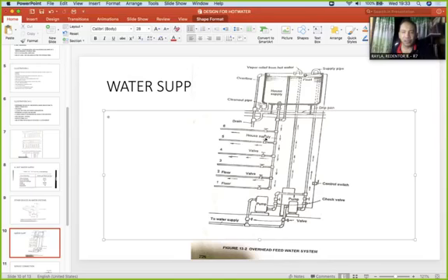No? Of course, you have an isolation valve for every story of the building. So you have the pump, you have here the check valve. For maintenance purposes, you can isolate that. If there are leakages, you can isolate. So this is now the formation of overhead.